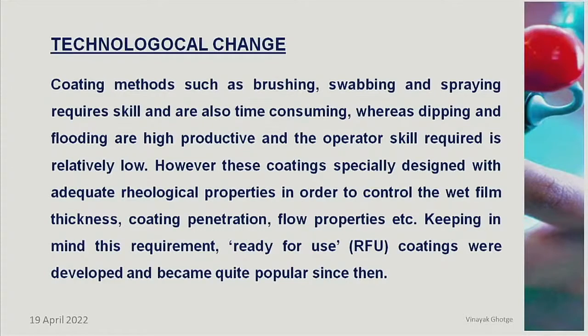The coating methods such as brushing, swabbing or spraying, it requires definitely skilled operators and also time consuming as far as productivity is concerned. Whereas the processes like dipping, flooding are highly productive and the operator skill required is relatively low.